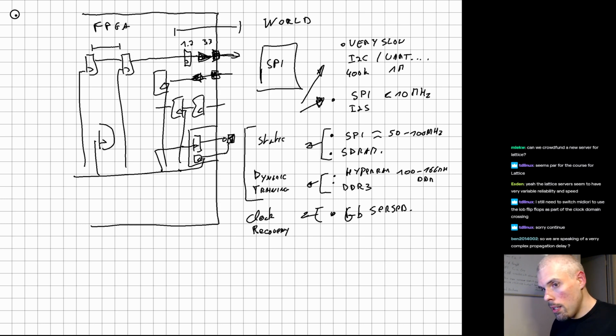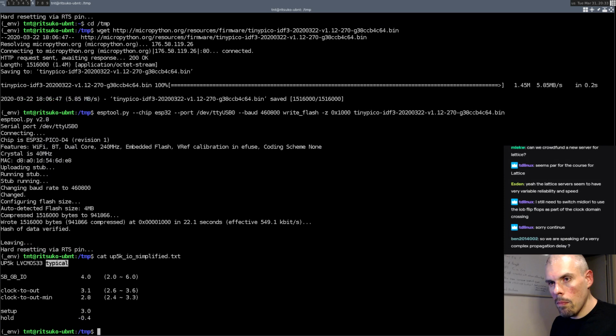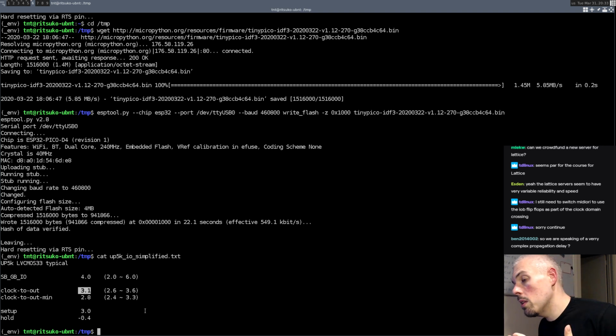And finally, here, I did put a range. I said the nominal value is 3.1, but I put a range between 2.6 and 3.6 because it depends on whether you're considering the best case timing, the worst case timing, or the typical timing. Usually I'll do the analysis with the typical timing and then look so that I have enough margin that I feel comfortable it's going to work in the other cases. In theory, you'd actually need to run the analysis we're going to do 3 times.